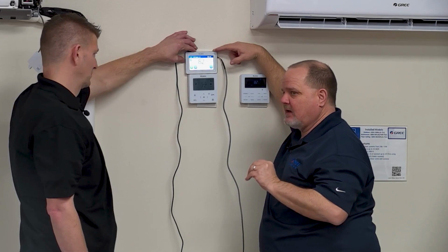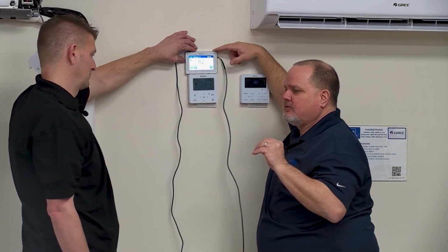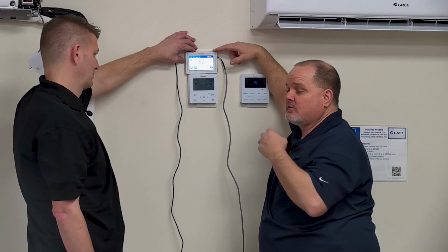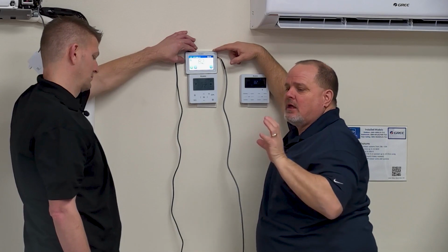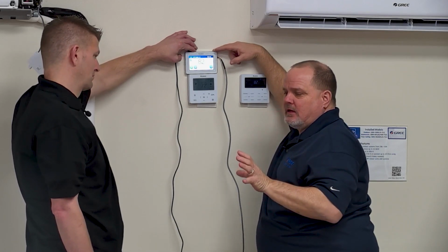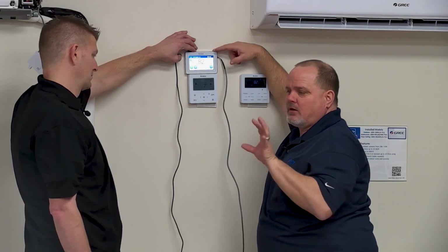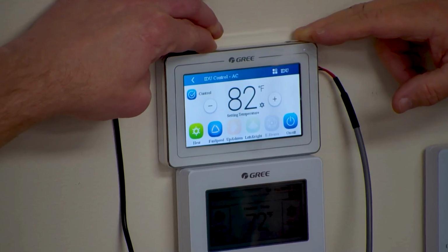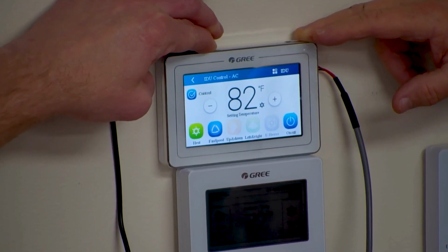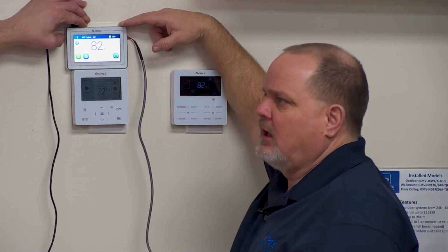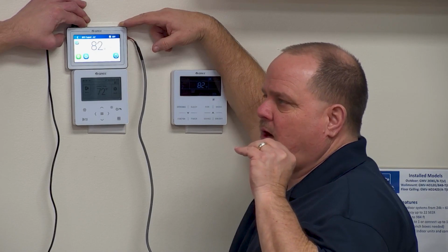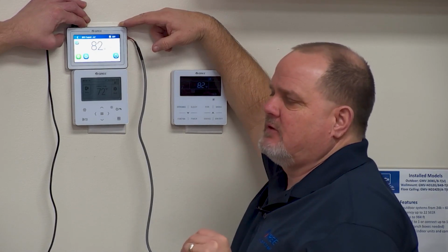What I mean by that is, with unitary product, in other words, standard systems we've always dealt with, when you put that thing in cooling mode, or you do profile setup on that furnace or that air handler or whatever, on variable speed, you're typically setting it to a specific CFM per ton, right? In other words, you're going to go to the dip switch settings, and say, I want this thing to deliver 400 CFM per ton. And it's going to try to ramp and achieve that 400 CFM per ton.